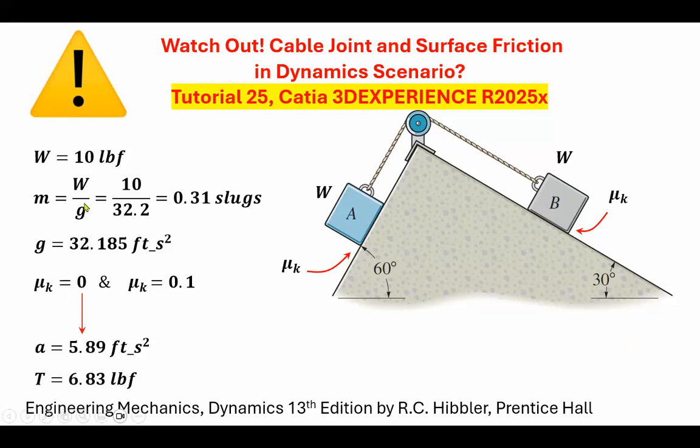Now, basically, hand calculation using Newton's second law applied to block A and block B, where the sum of all the forces equals mass times acceleration along the ramp, writing it for block A and writing it for block B, and realizing that, assuming this rope is inextensible, the tension in the rope is constant, and the pulley has no mass.